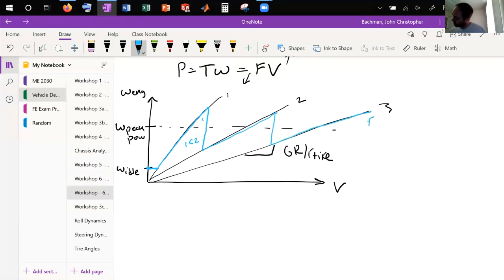And so this is like FSAE, right? And so you can see you don't get to sit at peak power the whole time. You got to bounce around it the whole time. You basically hardly are. Only a couple of, this instance right here, you're operating at it. This instance, you're operating at here. You're dropping straight through it during a gear change, so you're not operating there at all. This is basically an immediate jump. There's no actual time when you're operating there.